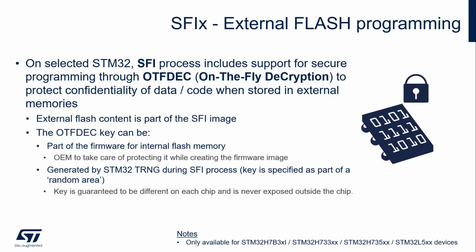An additional feature available for selected STM32 microcontrollers is the support for external flash programming, named SFI-X. SFI-X is based on the on-the-fly decryption peripheral, designed to protect confidentiality of data and code in external memories. The content is stored encrypted in the external memory, and the on-the-fly decryption allows for an on-the-fly decryption using a dedicated key. In the SFI-X scenario, together with programming the internal memory as described before, the SFI process can be used to securely flash the content of the external memory, and at the same time to protect the provisioning of the key needed for decrypting it.